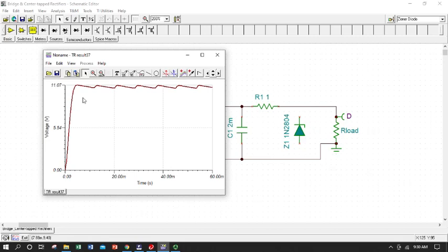So this is the voltage signal that the load sees. So this is what we care about. This is what our circuit that we're powering with this DC power supply sees. So it's seeing something on the average of, we can measure it. We're going to set our measurement bar to right about the midpoint of our ripple, and we have about 10.8, 10.9 volts is our average value, and some amount of ripple, not too bad.